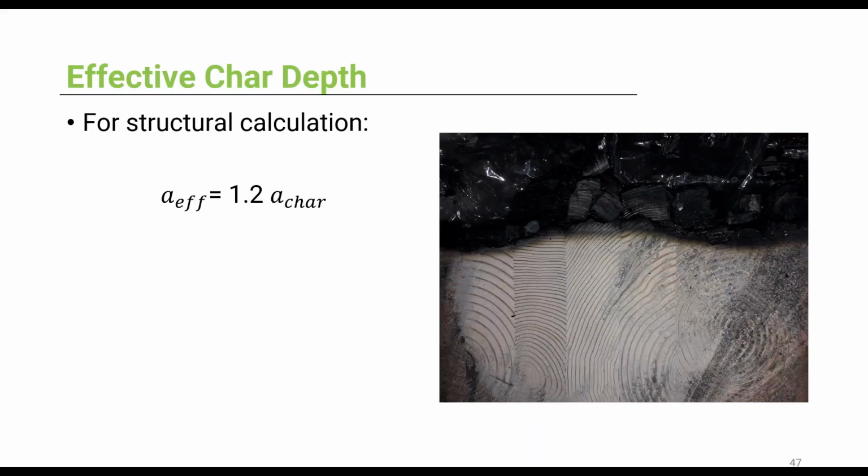Based on the TR10, to account for a reduction of strength and stiffness in the heated zone here, for structural calculations, you have to use an effective char depth. The effective char depth is 20% more than the char depth.